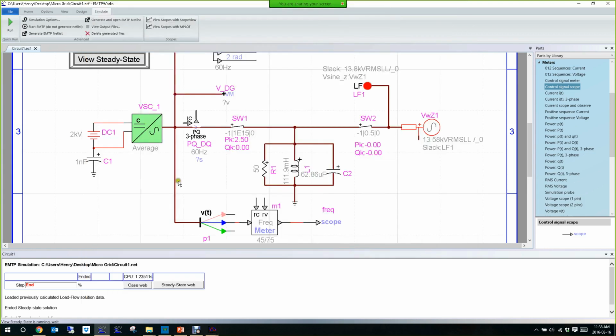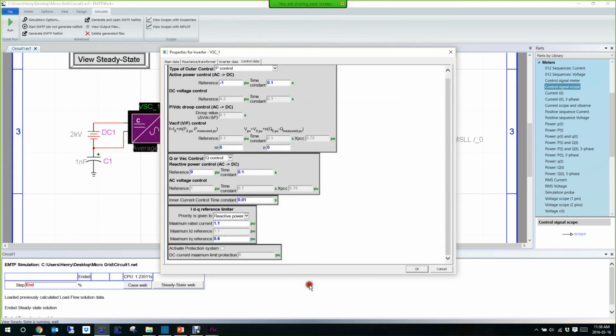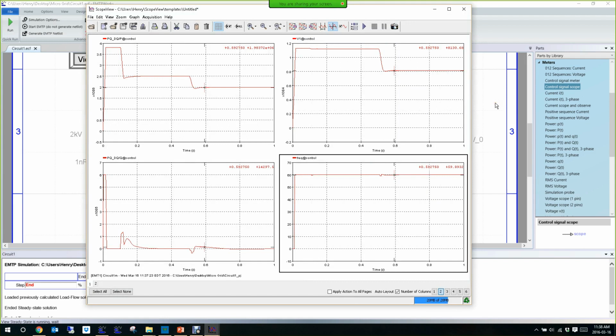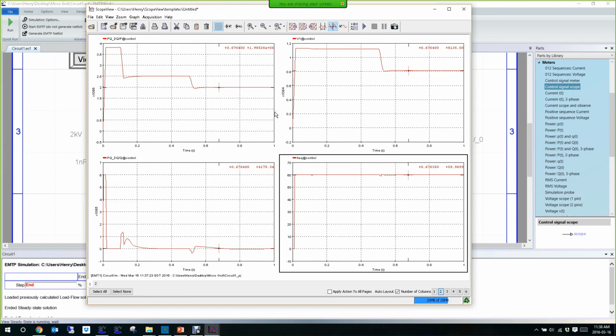The reason for that is that in my inverter, I have a section which is the IDQ reference limiter. And I have some limit here in the current and in the current in here. Since the voltage drops, to ensure the same amount of power, I have to inject more current. In that case, I reach the limit, so I cannot inject enough current. That's why the power of the inverter drops. So it's interesting.